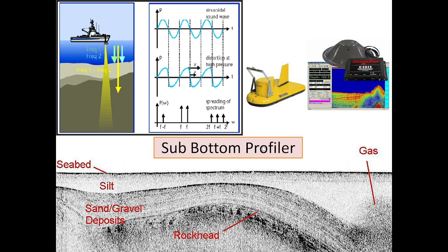Then sub-bottom profiling. In sub-bottom profiling, the main technology is that you give different energy to your pulses and a different frequency. Frequency 1, frequency 2. Now frequency 1 plus 2 will have a different penetration. So this is the sound physics, but anyway, let us not get into it. Basically, the absorption and the reflected energy tell you what type of material it is. So the classification is taking place with human expertise.